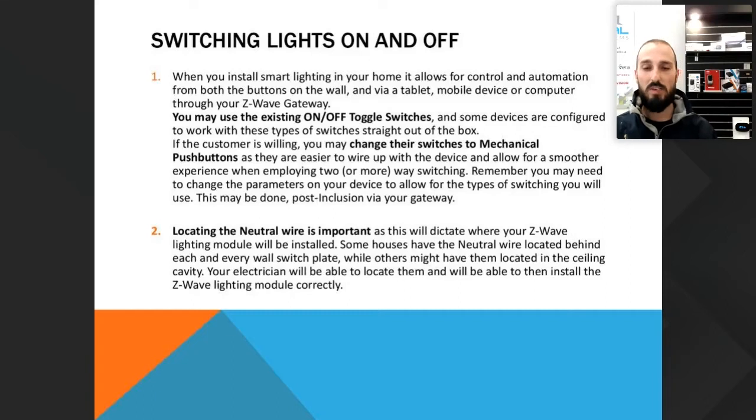The reason why we say that you need a neutral is that a lot of devices cannot run without a neutral line going into the switch. So if you don't have neutral available at all in the premises, which is a rare occasion, there are certain devices out there that you can use, but you are quite limited in terms of what you can use in that kind of setup. So for us, we always say it's best to have neutral.